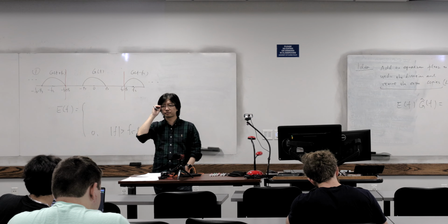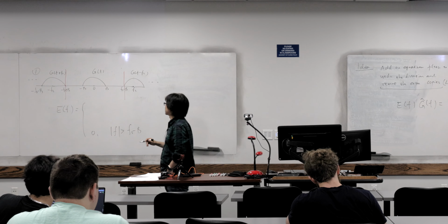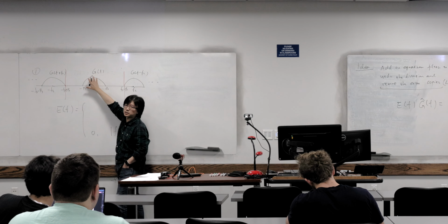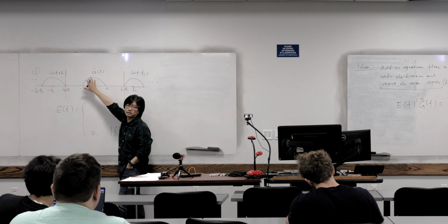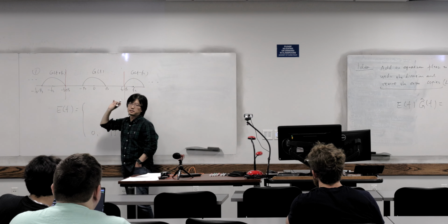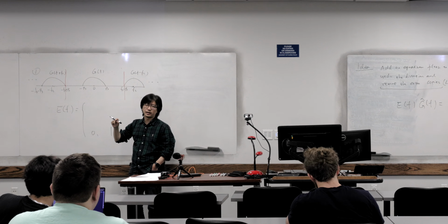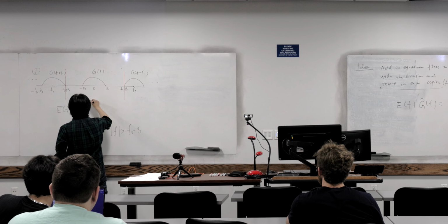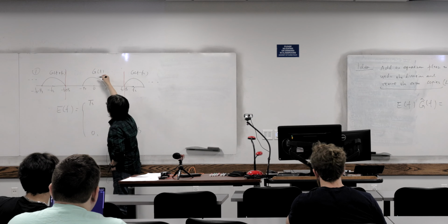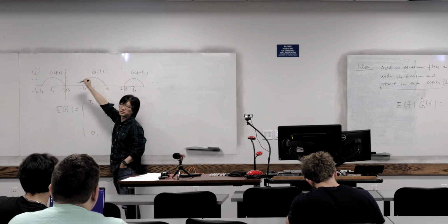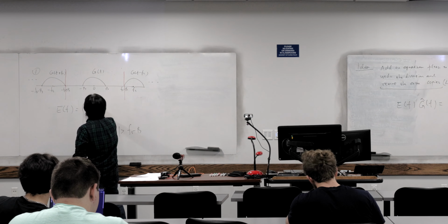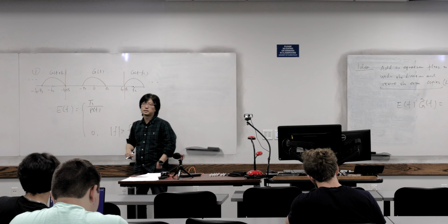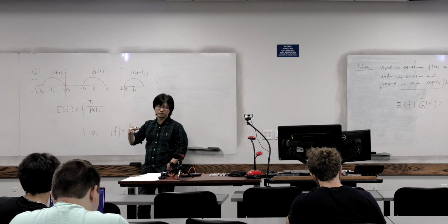The next thing is, how about the middle part? For the middle part, we need to get rid of the distortion completely. Let's see how we can get it. We need some scaling here, because we have a 1 over Ts, and then we need to divide by P(f), because we have something multiplied by P(f).